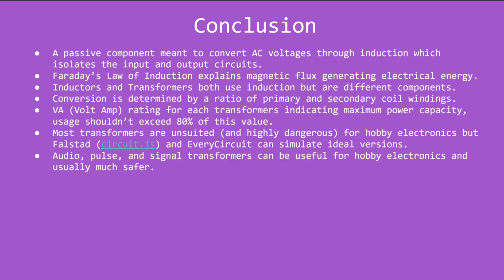There's a volt-amp rating for each transformer indicating the maximum power capacity, and usage generally shouldn't exceed about 80% of that. Most transformers are completely unsuited and maybe even really dangerous for hobby electronics, but you can use circuit simulators to simulate ideal versions.